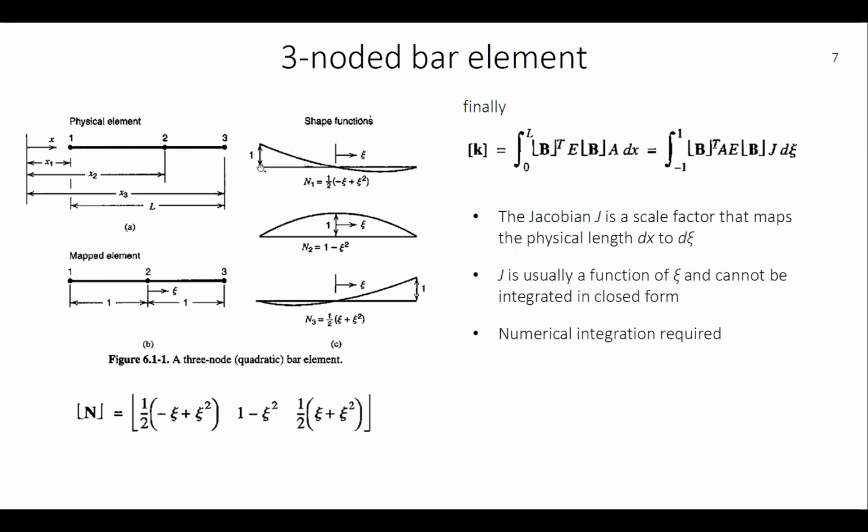So the shape function at node 1 needs to be 1 here, and 0 in the other positions. And for having a C0 element, we need to have a continuous displacement field. So we cannot have any kinks in that.